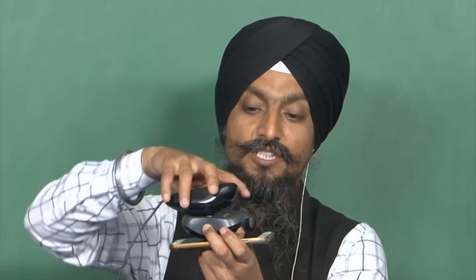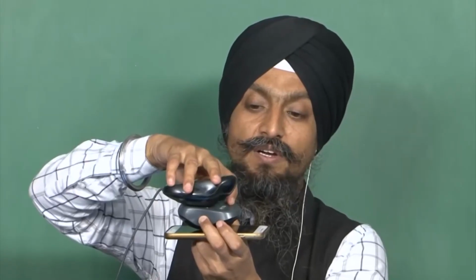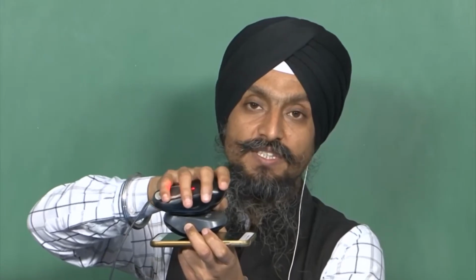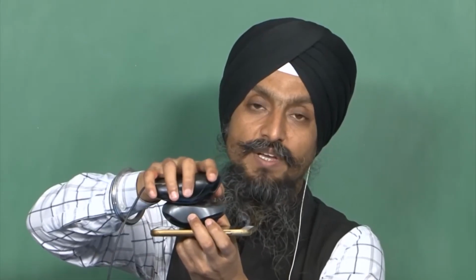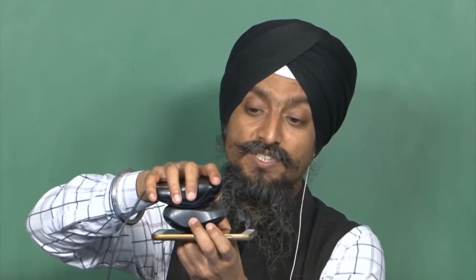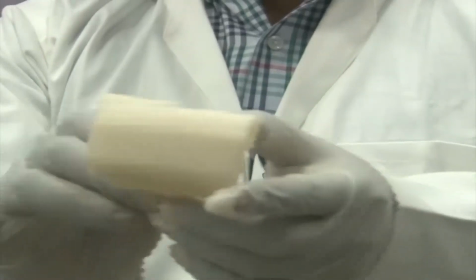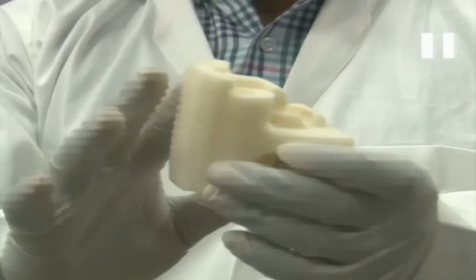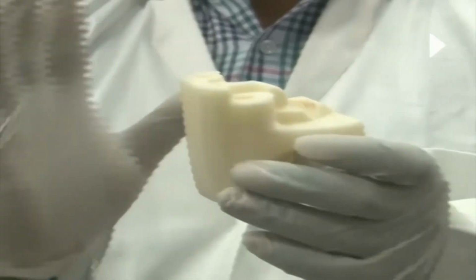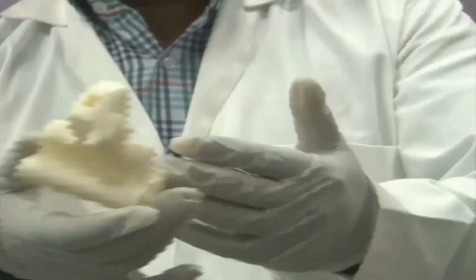If another thing is manufactured here, the portion in between is not touching the bed, but it will provide support here as well, because it has to produce this as well. In case of touching bed, it will provide support here only. In case of everywhere, it will provide support here as well. So for complicated models, we use the option everywhere. Now the software is responsible to fill the support wherever it is needed.